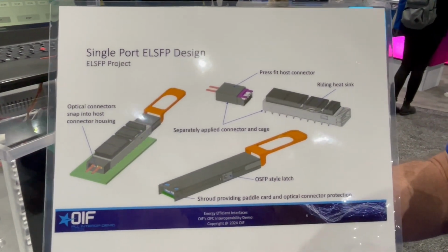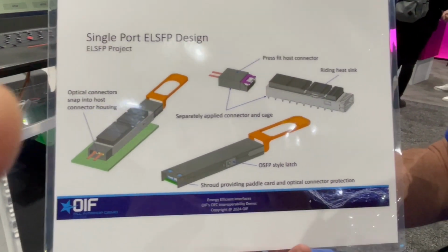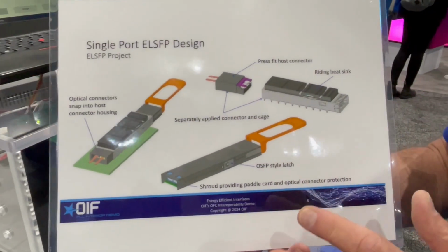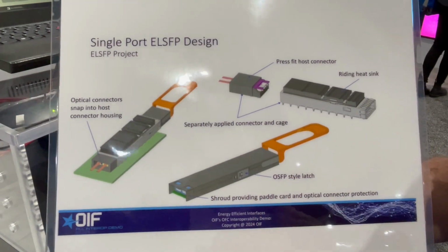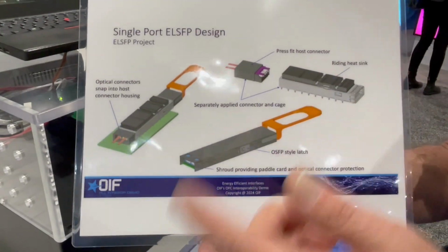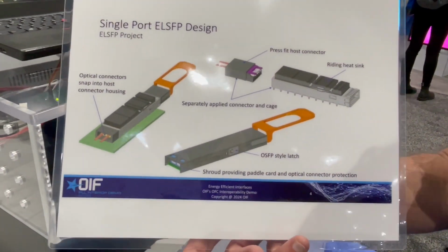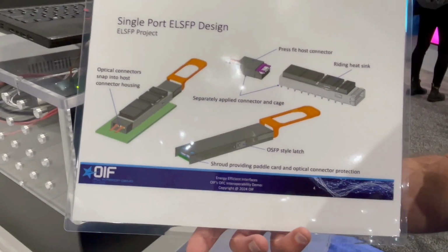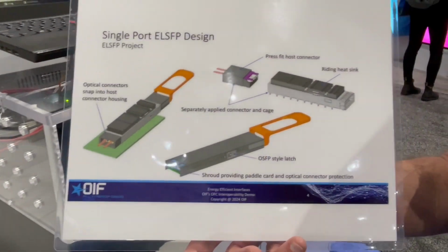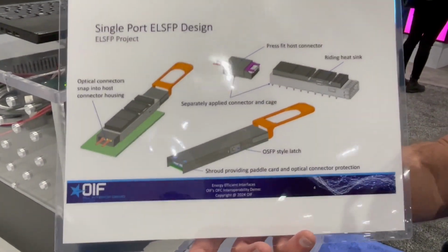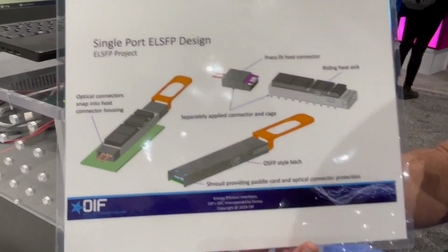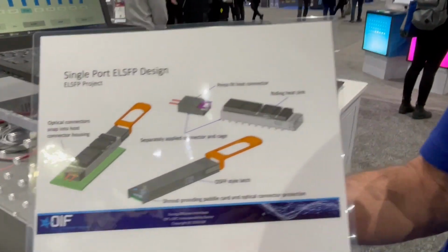So does it first make the electrical connections before it makes the optical connection? Or is the optics or is the laser already on? No, the laser can't be on until it's powered up, but I imagine there's a time delay by the time the power is put on before the internal electronics catches up and starts driving the laser. So that ensures that when you plug it in, the laser is not active. Right. And then only when it's plugged in does the laser become active. Therefore, you can't look at it directly. That's right.